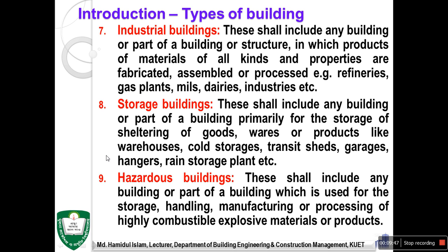And number 9, hazardous building. This shall include any building or part of a building which is used for the storage, handling, manufacturing, or processing of highly combustible or explosive materials or products.